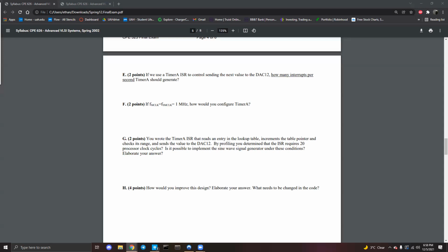The math here is relatively simple. So go back to all that timer information. Where did we fundamentally get that? Well, actually, no, we know. Previously we just did the calculations. 1 megahertz divided by 20,000 minus 1 equals 49. But if we're just talking about absolute speed here, it's actually 50 instead of 49. So that's 50 clock cycles. And we've been told the ISR can operate in 20 cycles. So really, yeah, we can speed it up a heck of a whole lot. We could double the samples and there still wouldn't be a problem.